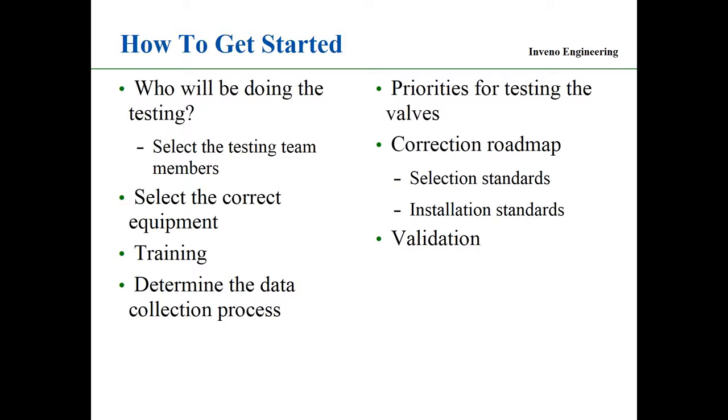The thing is priorities for testing the valves. If I have to go and test 20 bypass valves, and I come back and 10 of them are leaking, what degree of leakage? So I set priorities. The ones with the highest ultrasonic level or flow are the ones I'm going to do first. The ones with very low ultrasonic levels are lower priority. So I set priorities depending on my test results.